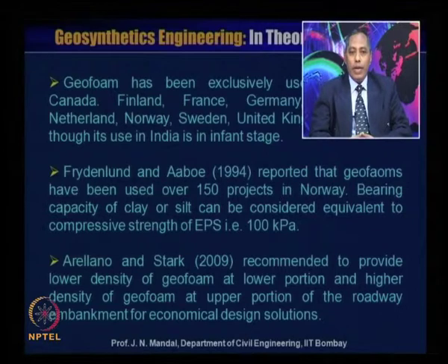Bearing capacity of the clay or silt can be considered equivalent to the compressive strength of expanded polystyrene, or EPS, and that is 100 kilopascal. Arellano and Stark 2009 recommended providing lower density of geofoam at the lower portion and higher density of geofoam at the upper portion of the roadway, for an economical design solution.